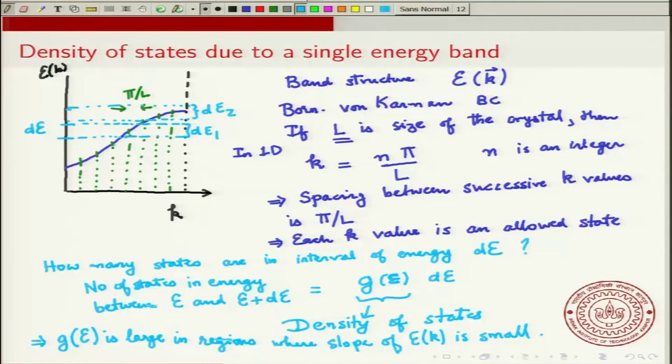Now the other point I want to make, I am just going to erase this thing here, is that often in the books and journal articles, the band structure is shown, and then side by side right here you show the density of states. Now, because E is an axis for the density of states, the g of E is actually plotted here. Let me erase this. So g of E is plotted this way.